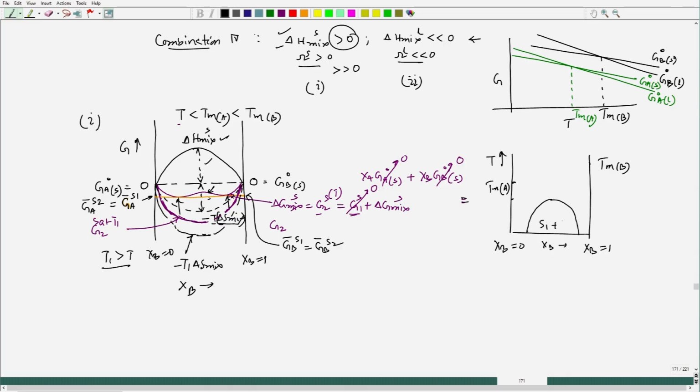and here we have S1 plus S2. Fine. So, we see, and this is the point where we reach criticality of temperature, where the inflection in the free energy curve with composition is just starting. Okay. So, that is what we are actually meeting at one point, and after that the inflection will keep on expanding. Okay. So, in fact, if I decrease the temperature, this plot would be, if I do it with a different color, like this.